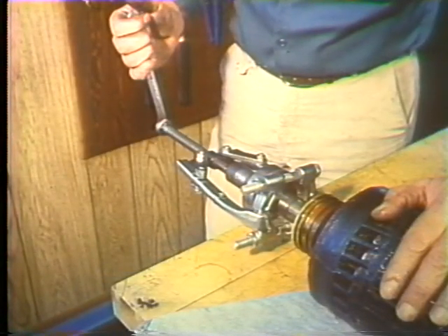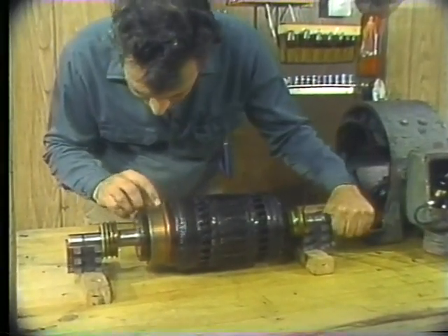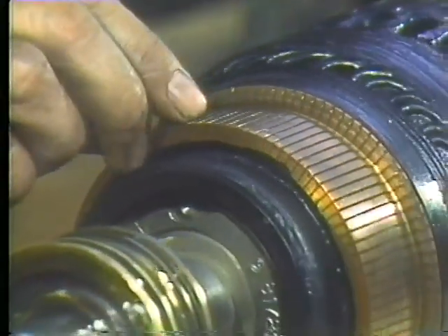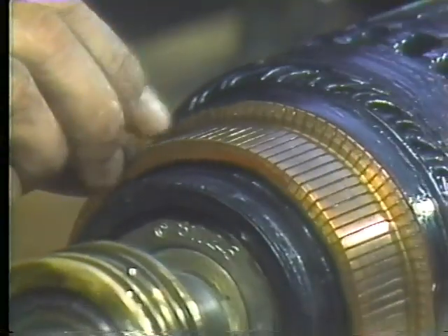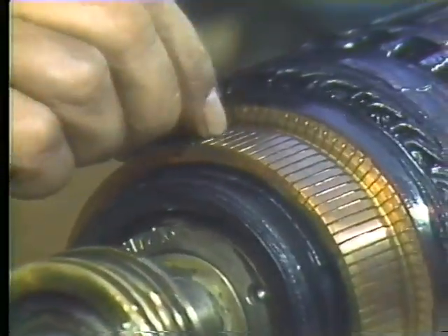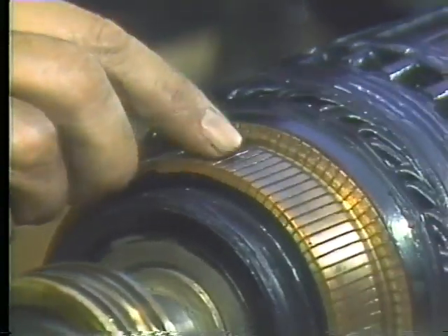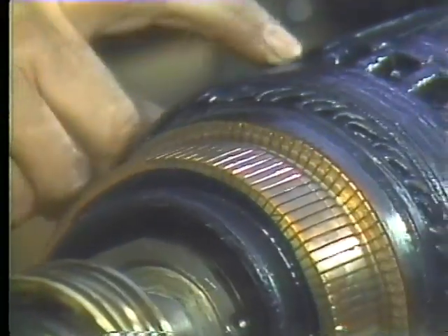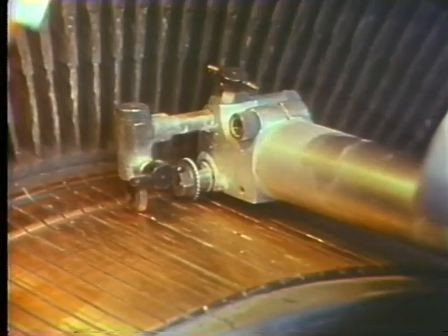Well, the motor's apart. The next step is to inspect it thoroughly and give the parts a good cleaning. We put the armature in a set of V-blocks so we can look it over. Look for evidence of the types of problems we went over earlier. Check the level of the insulating material between the segments. It should be about 1/32 of an inch below the level of the segments, certainly not lower than 3/64 of an inch. If the level's too high, you'll have to undercut, and you can do it by hand or with a power tool specifically designed for this purpose.